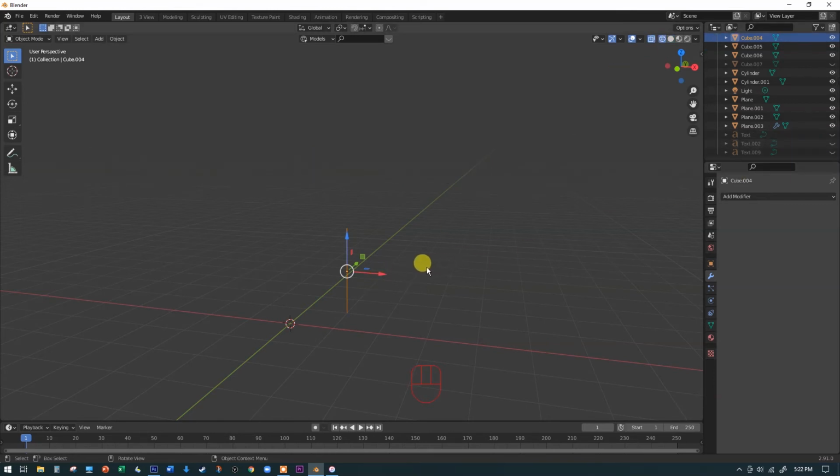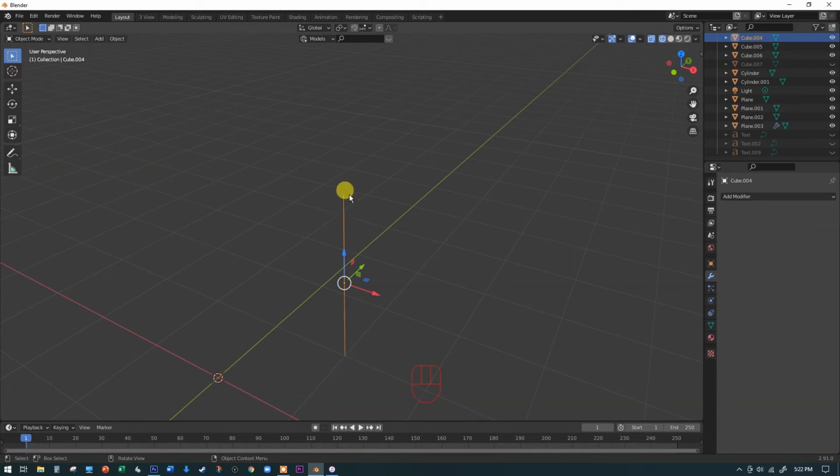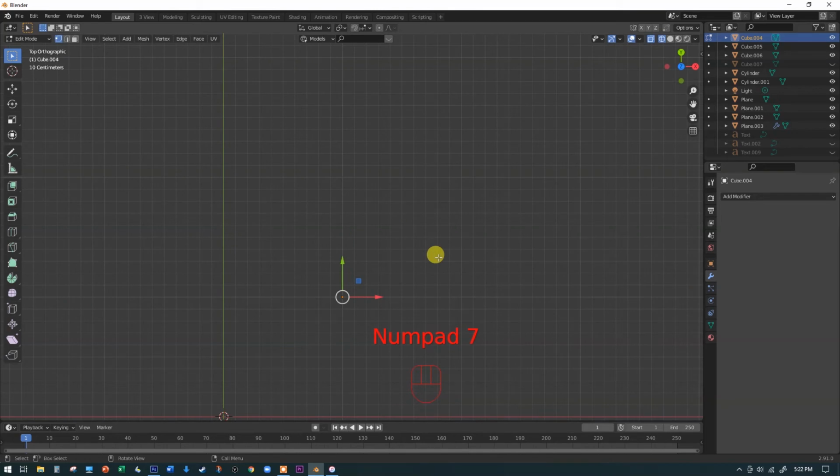Let me hide the title. And I've got the little wireframe edge of this wall. Again, probably easier to do in top view, so I'm going to jump over into top view, and I'm just going to hit extrude, and now I'm extruding off both sides of the wall.